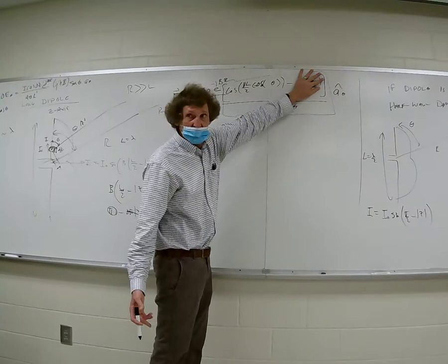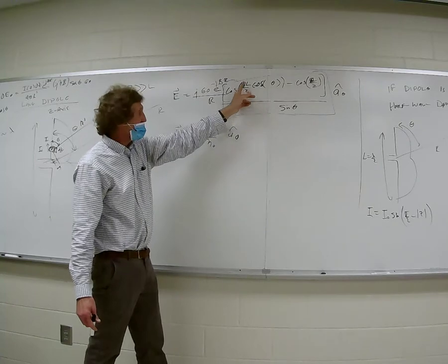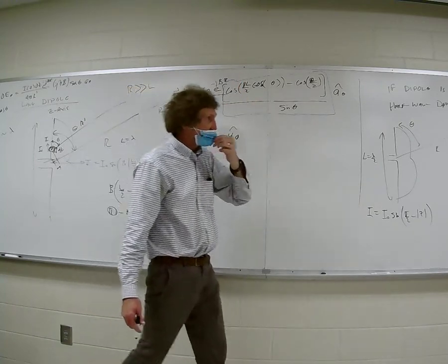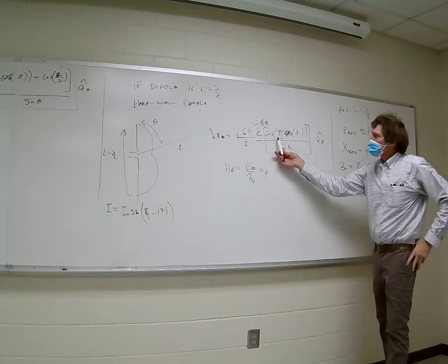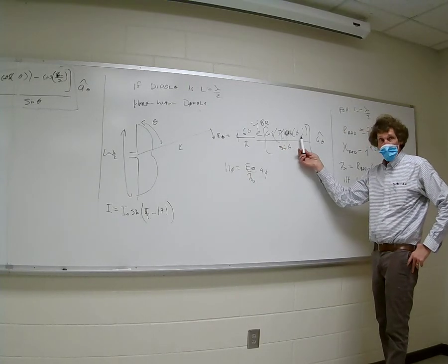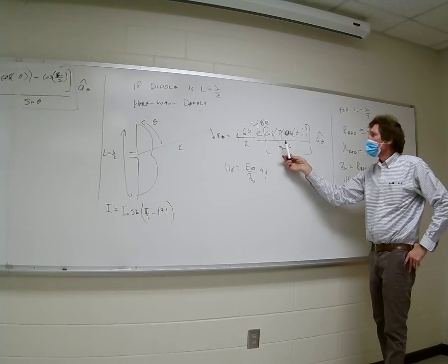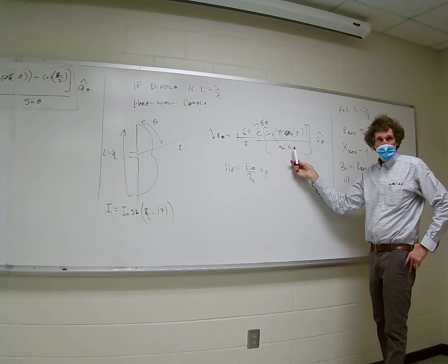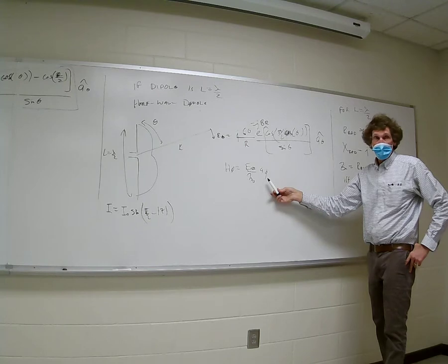You follow me? Now, up here when I have beta L over 2, that's simply pi over 2. And here's what happens. That angular function reduces to just cosine of pi over 2 cosine of theta, divided by the sine theta, for a half-wave dipole. Make sure you know this. Write this down. Okay? We're going to talk about that pattern. That's the E field, and the H field is found by just taking the E field divided by eta. This is all far field, okay?